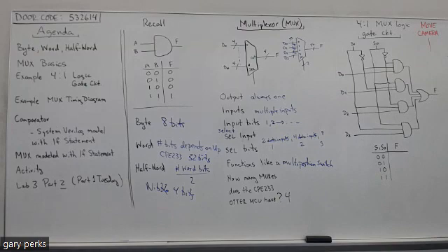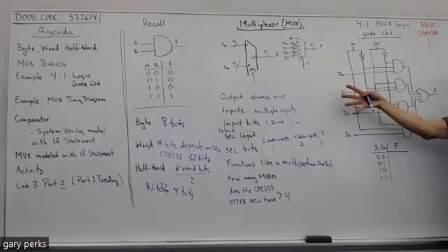Because the next thing we're going to do is look at the actual gate logic. Here's the logic gate circuit. CKT, by the way, that's my abbreviation for circuit. I don't think that's anyone else's. So this is a 4-to-1. What the 4-to-1 refers to is that there's 4 data inputs and 1 output. And like I said, muxes always have 1 output. So you either have a 4-to-1, an 8-to-1, a 16-to-1, 6-to-1, whatever it may be.